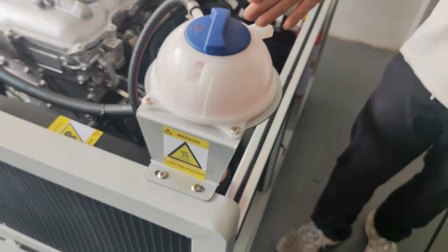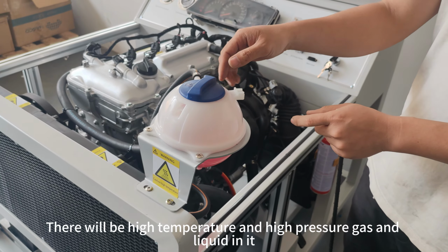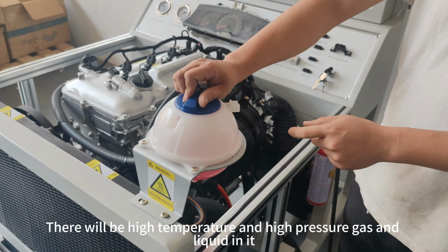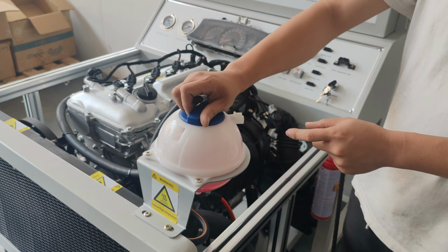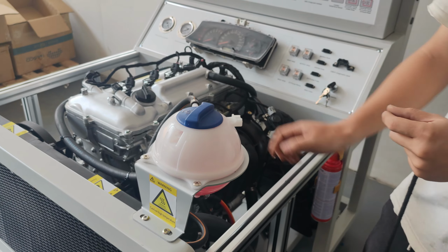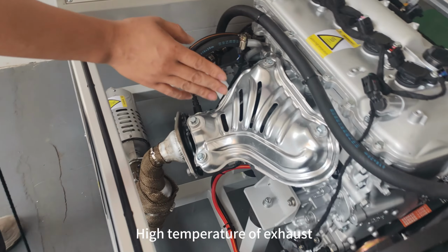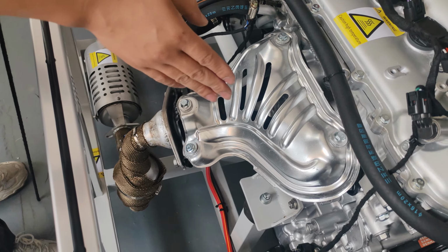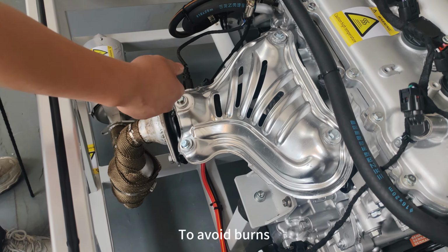Then when our engine runs for a long time, there will be high temperature and high pressure gas and liquid in it. Then we must not open this lid during the training process. And this side, the high temperature exhaust. During our runtime, do not touch this high temperature exhaust pipe with your hands to avoid burns.